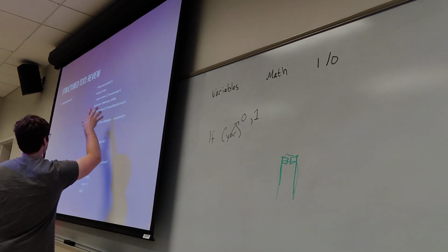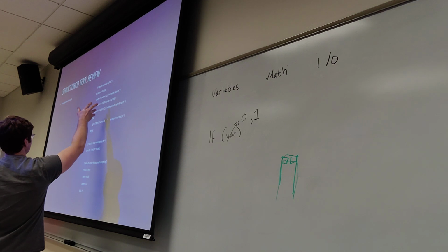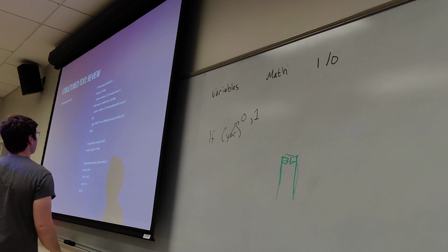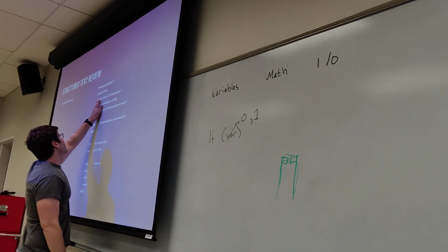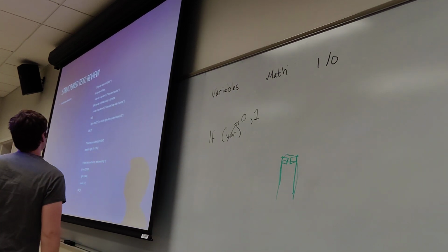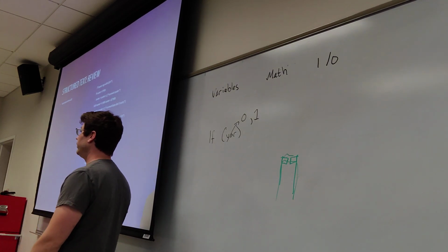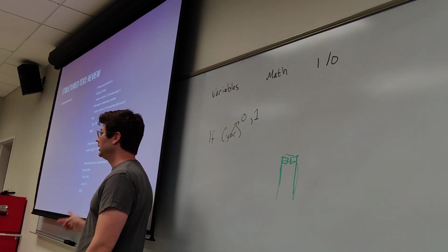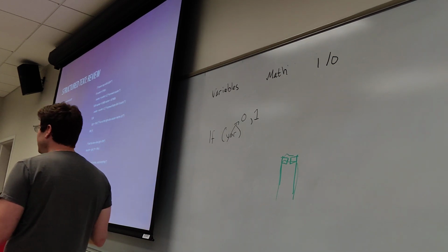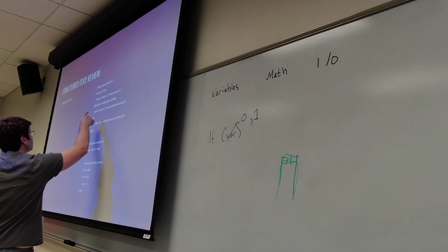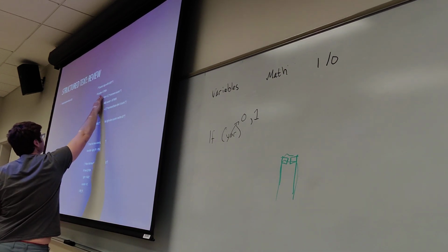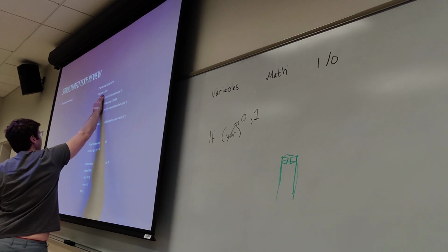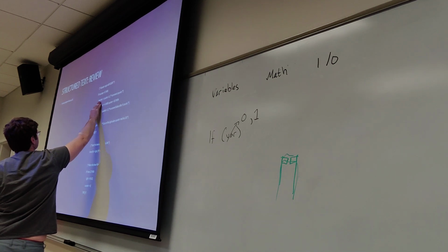Okay, if you need to know how to spell something, how to work with greater than, less than, it's a really good reference right here. Okay, so our first one right here is a simple counter. Maybe we are setting a counter in our slow task group that counts up 1 every half of a second. And then we say, okay, when that counter hits 10, we do something meaningful. So we say if our counter variable, which is counting up once every half second, is less than 5, so essentially while our counter is less than 5, then do this next line.